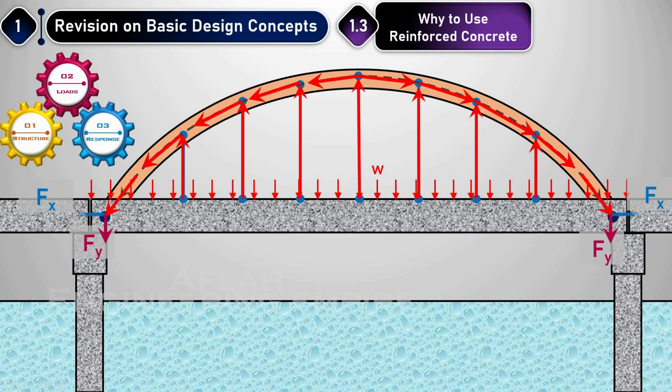Okay, now if the horizontal component effect is very large, it means that this deck will surely suffer tension force. So it may not bend like we said in the simply supported beam, because this deck has got cables at some interval that will transfer the dead and the live load from the deck to the top arc. So for this, the bending due to the loads may be very small. However, finally the load comes here. If the horizontal component is very large, this whole component, the deck part, will be under high tension.